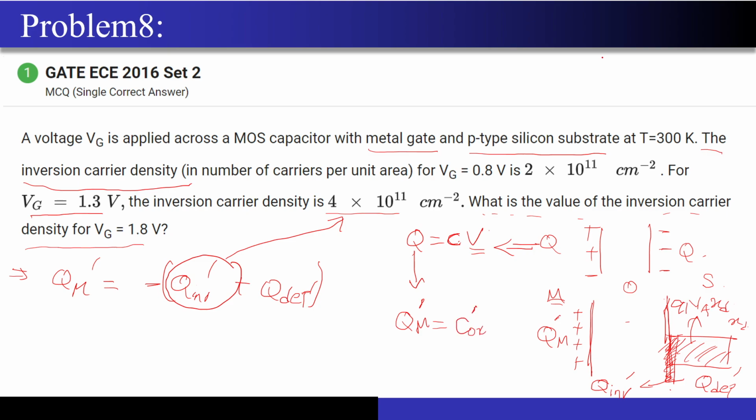We have seen that CV curve, it falls and it comes back over here, right? After this is nothing but your Vt point. So now since the inversion layer has formed, whatever voltage change that will apply over here will be reflected by this change in the inversion layer charge, not with respect to the depletion charges, right?